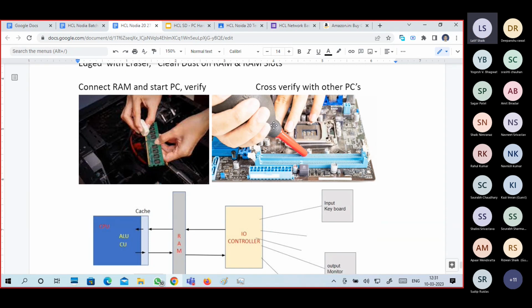Okay, guys. So you got a POST error, power on self test failed, meaning when you start your PC, the system is not booting. It is showing only power LEDs blinking, not keyboard LEDs, or nothing on your screen, and you may hear no beep sound or multiple beep sounds. What can we do?